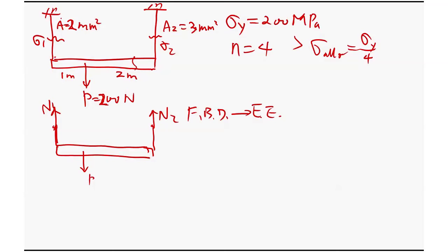So you have sigma Fx equals 0, sigma Fy equals 0, and sigma M equals 0. Or you can have MA equals 0, MB equals 0, MC equals 0. So whatever the combination, you have 3 independent ones. Okay, so what's the easy one here? Sigma Fy equals 0, right? What about sigma Fx? There's nothing there, no load, so automatically it's 0.